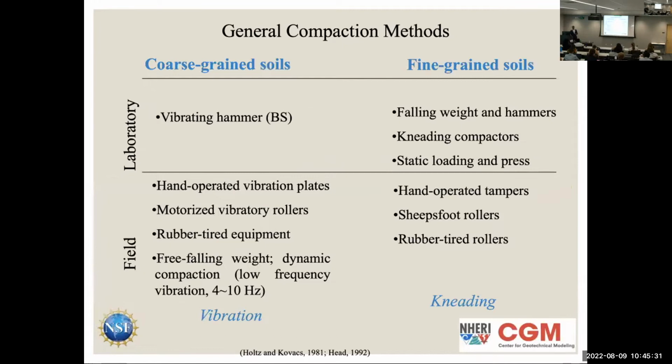Basically, the difference between coarse soils and fine soils is that with coarse soils you can see the grains with the naked eye, while with fine soils you can't. Fine soils, when you wet them, also have a smoother texture and you can kind of mold it, while with coarse soil you can't really do that.